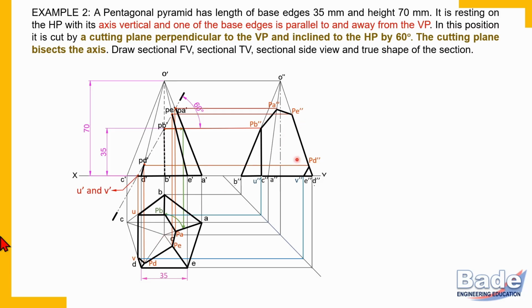One more thing I want to tell you. PB. Do you remember how we transferred PB? Take the PB point on the boundary edge by a horizontal line, project it in the top view on edge OA, and then take it back to its original edge. If you have a side view, then you can transfer PB from the side view also. This is the front view of PB.